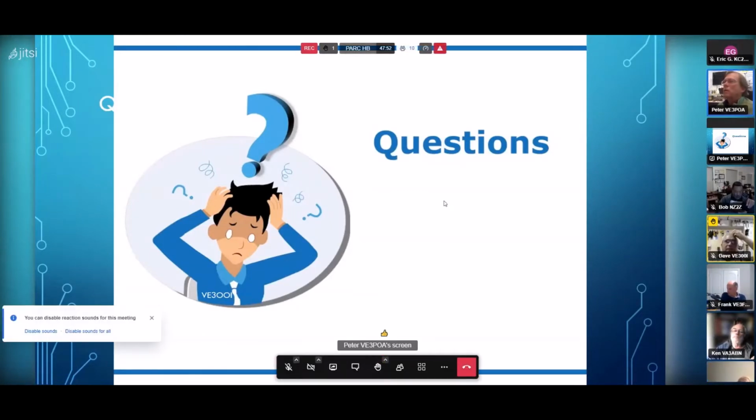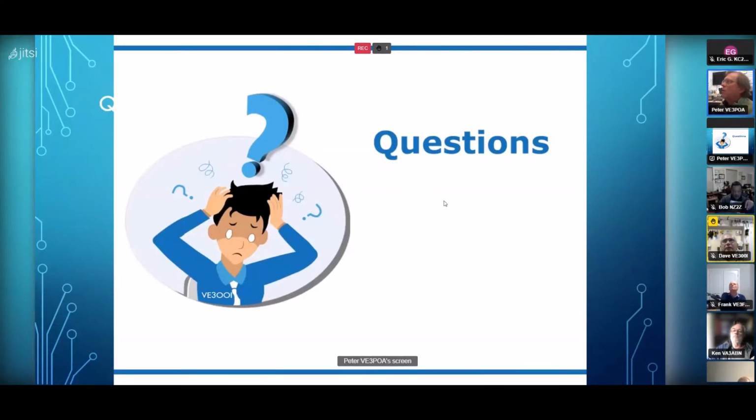Yes, I think so. I don't know exactly. I should probably go back and take a look and see what they did. They show an application circuit, but I don't know if they show the circuit they use for testing. I'd be curious if you took the chip out of the board and put your SA on it and see what the nominal impedance is of the input circuit and the output circuit, and how that varies, and is it related to your 1.3 dB variations that you're measuring? Don't know. I think further exploring, I guess.